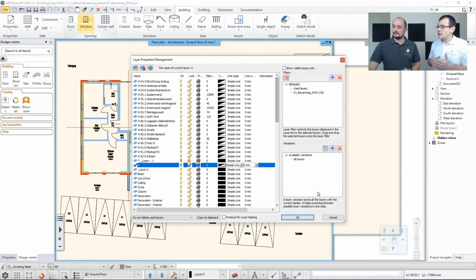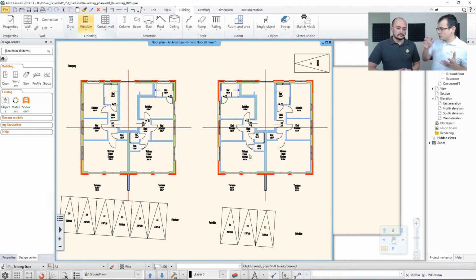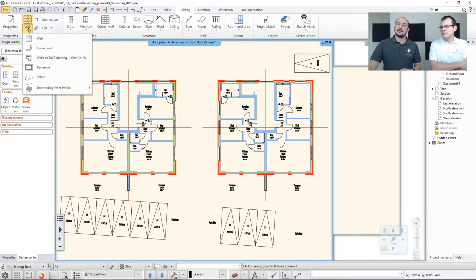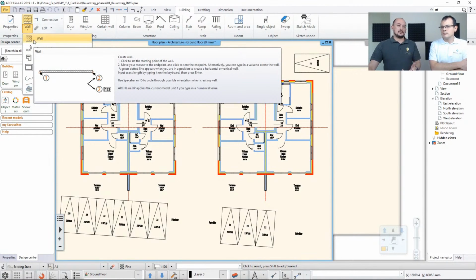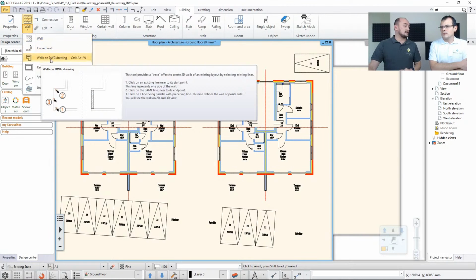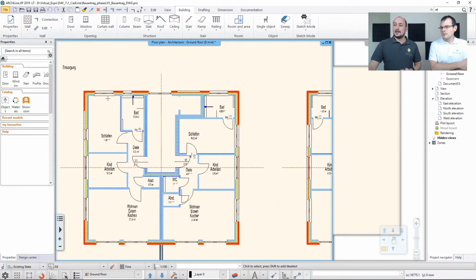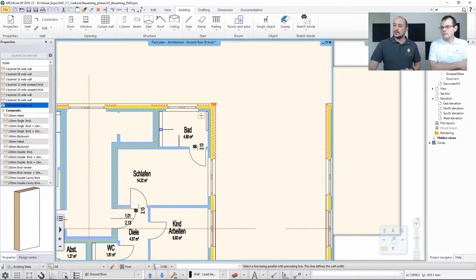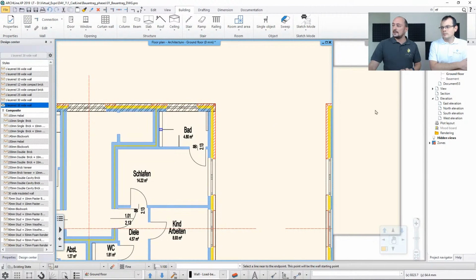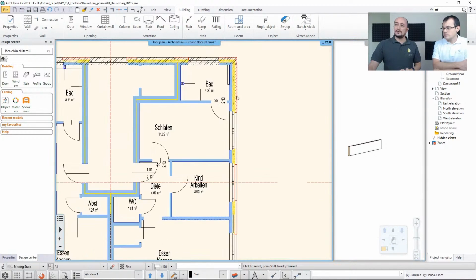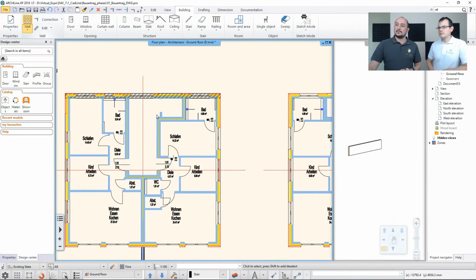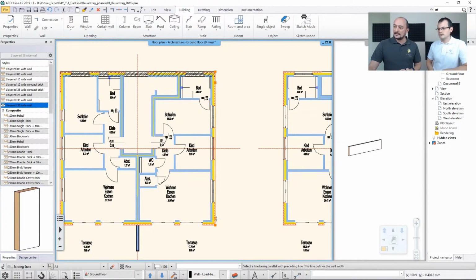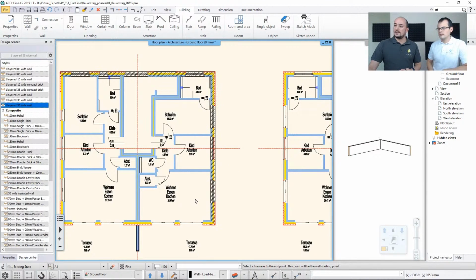Okay, we have the drawing, we turn it into a 3D model. Do you want to show that or jump straight to the levels? Well, let me just show you one simple example, and then you will understand the idea how it was created. Besides being able to create walls on their own individually, you can also process the DWG drawings, and you can say, okay, so now what I have here, this is one part of the wall, this is the other end of the wall, and this is actually the thickness. So the software will quickly turn that into a wall, and then you can just go there and keep repeating this.